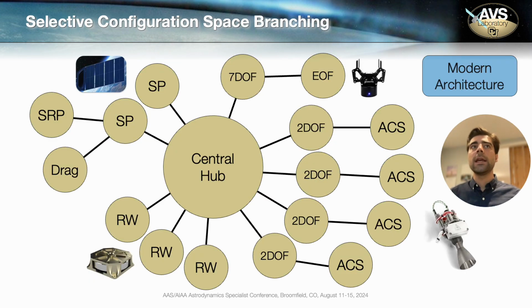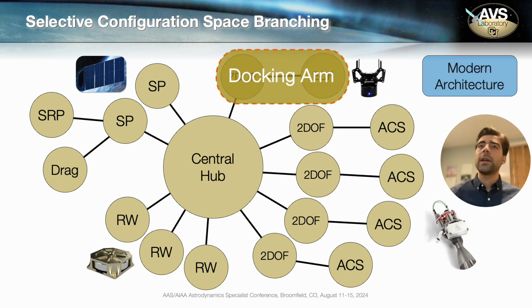And it's not to say that we can't model some of these more complex components on spacecraft using the existing back substitution method, but now knowing that we need to have no explicit cross coupling between our components, the way you would have previously had to do that is by considering these to be one component each and derive a set of equations of motion that are specific to it.